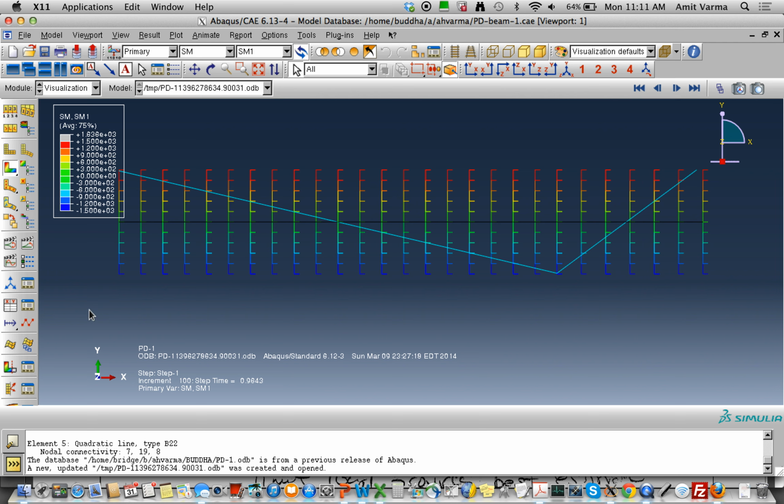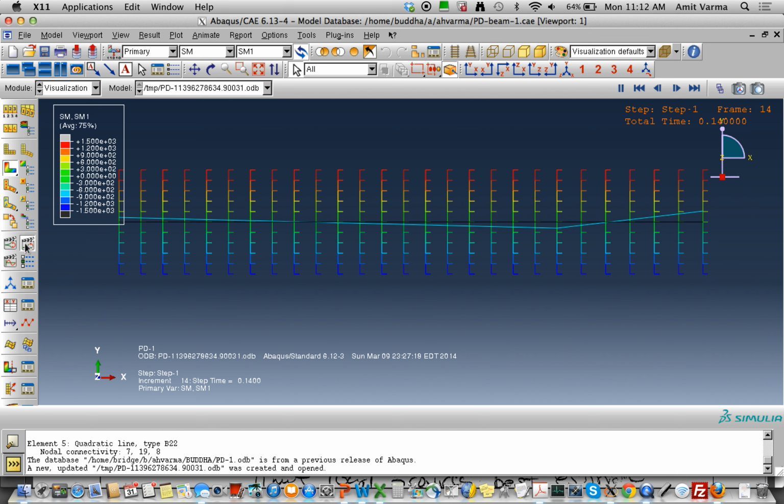And if I wanted, I could look at how this is happening. I could probably run a video, and it's going to show me how the bending moment diagrams are working. You'll see one of them hit 1500. It will probably be the same one that occurred first. There, that's hinge number 1. Then that's hinge number 2, and then the final hinge occurs at the end.